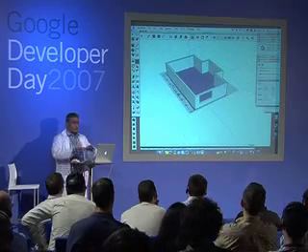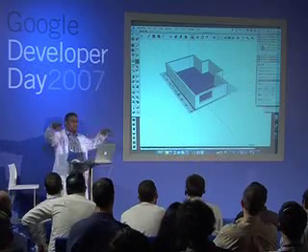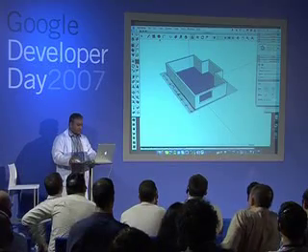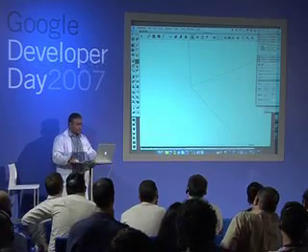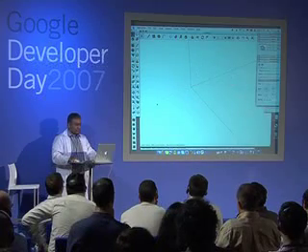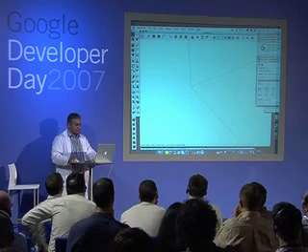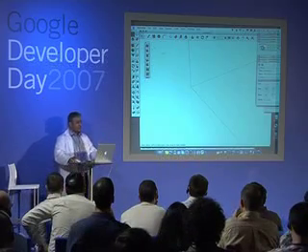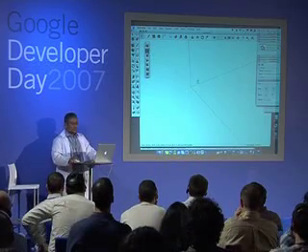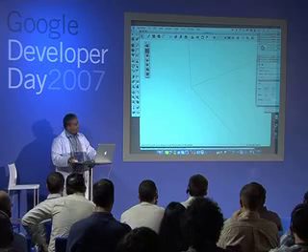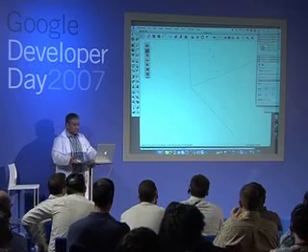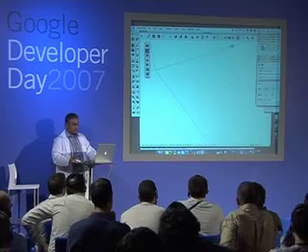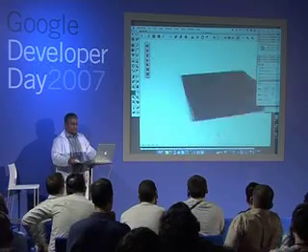Okay. I can use SketchUp to create terrain if I wanted to. Okay. With terrain, we have a tool called Sandbox. Okay, this is the tool palette. I will show you how simple it is to create terrain on that. So I'm going to use the grid, and the grid spacing is roughly 3 meters at the moment. So let's just create a grid so big.